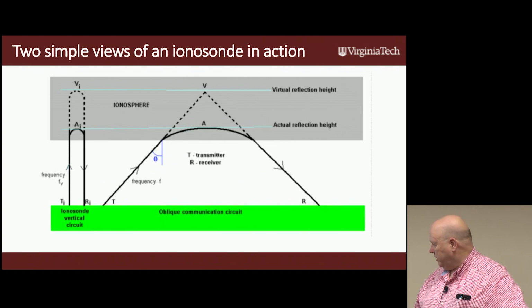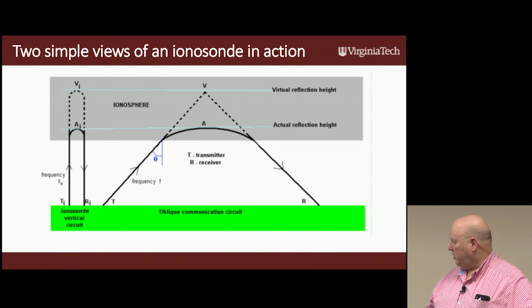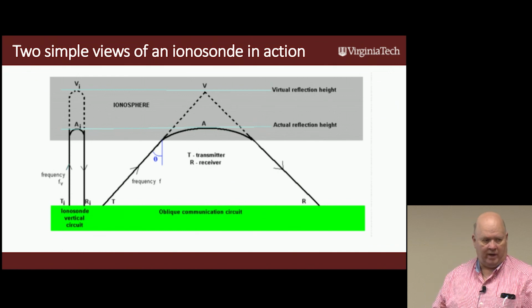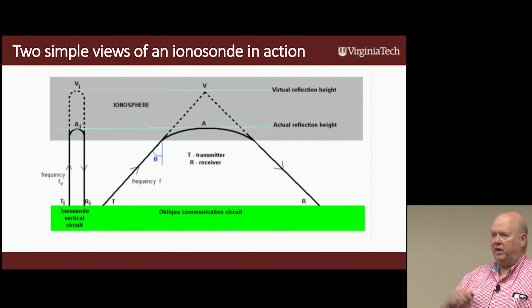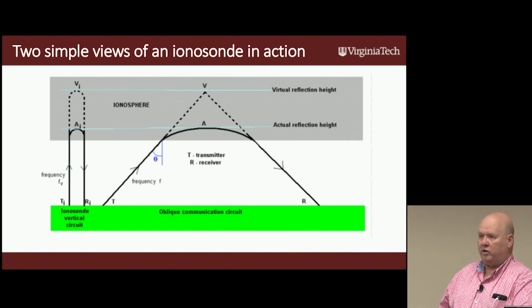So the way it works is, at an agreed upon time, you transmit a pulse. The pulse travels up to the ionosphere and back. By the time it gets back, you have already guaranteed yourself that your transmitter is off, your receiver is on, and you can hear the return pulse. And so what do you do? You correlate for the transmitted pulse in the receiver. That's done down in the software in GNU Radio.